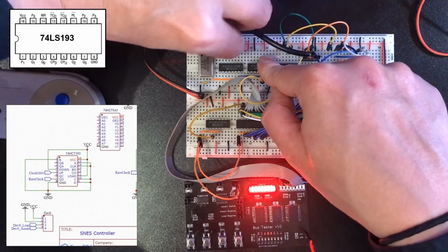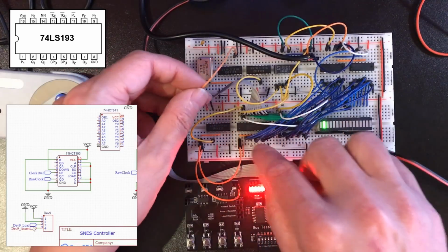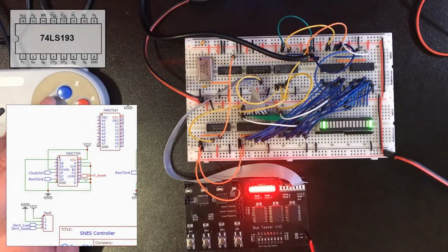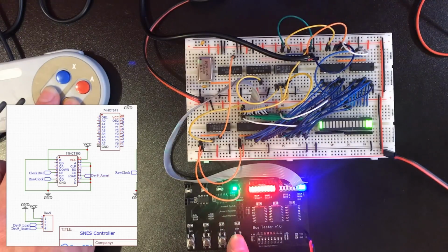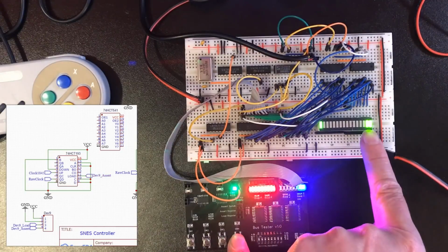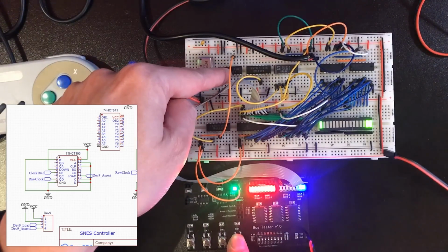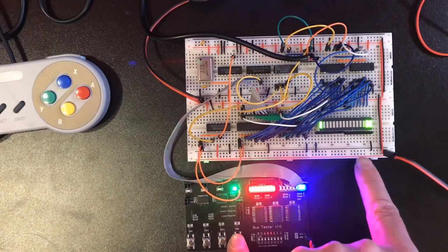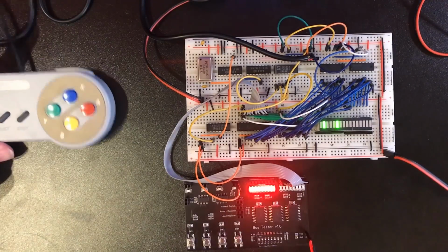Now, instead of pulling the load line on the counter up, we'll have a line that we take from our load input. Right, so if you think about what's happening here, now that was loading the top half, let's load the bottom half. Even if I let go here, these outputs are not changing because the clock signal here is no longer being generated, and more importantly, the latch isn't being generated. And as soon as I release, it returns to normal operation and the status of the LEDs change.